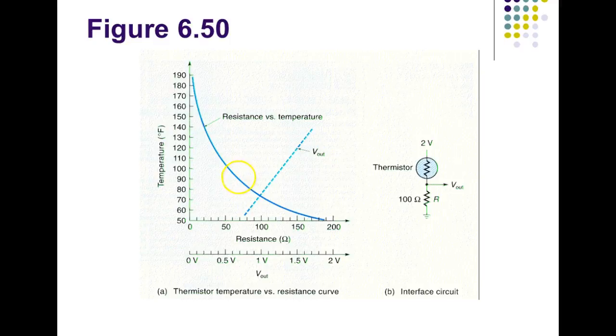Might get down to about 60 something degrees, so that'd be right here, and then it might get up to 80 something. Well, if you look at that, the curve is what? Pretty dang linear. So we have no problem in a house, because the range span of a house is so small, we don't have to compensate for it, because we almost get a linear curve there anyway, right? You understand that?